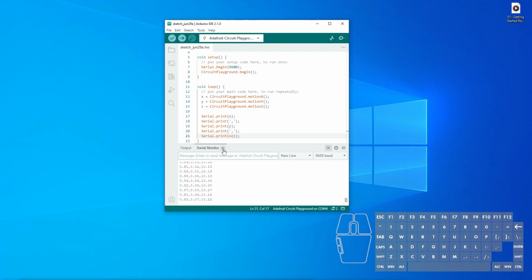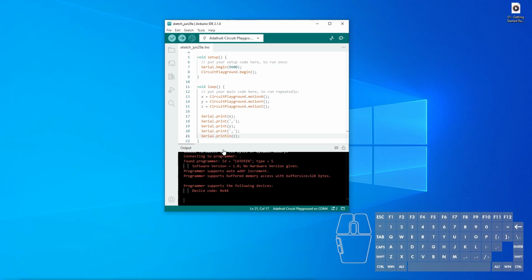I'm going to close that serial monitor because if it remains open, then it's going to block the data from getting into Unity. So every time you have the serial monitor open, all of the data is going to just go to that serial monitor. So if you're ever working with serial data, which you'll likely encounter for a lot of microcontroller projects, make sure that you close that serial monitor. Otherwise, your program may not work properly when it's actually running.